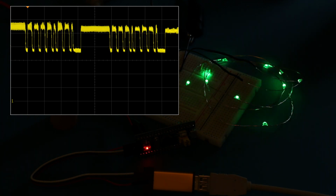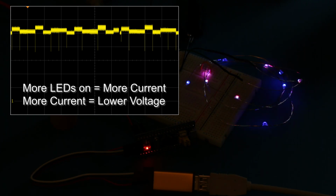I've now implemented a simple state machine which will pick out which of the colours need to be turned on based on which colour is currently active from the 8 available. Each iteration through the loop will step the colour on by 1 and then transmit the address and the colour for each of the sets of LEDs. Looking at the scope trace while we're running this program, we can see the same step pattern that we saw previously based on which colours are active.